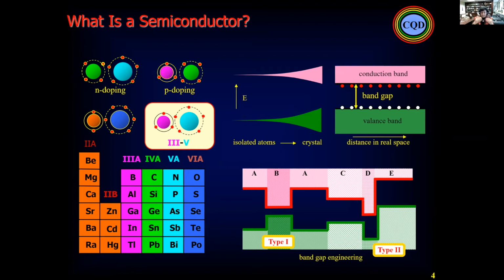And what is important about these III-Vs is that they have covalent bonding, they have a direct energy gap, and at the same time, most of them have the zinc blende structure. So it's excellent for semiconductor lasers and, at the same time, detectors.